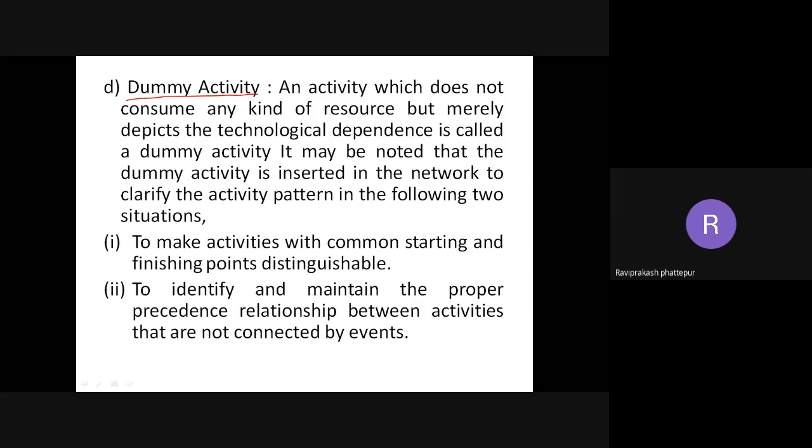As I told you, work could be happening simultaneously, but in some places the painter has to wait. If he paints initially, there will be drilling and cutting, and he has to paint that wall again. So first we complete the electrical and plumbing work, then the painting is done at the last, so that no mess is created by the plumbing and electrical work. To show this precedence and succession, these dummy activities are used.